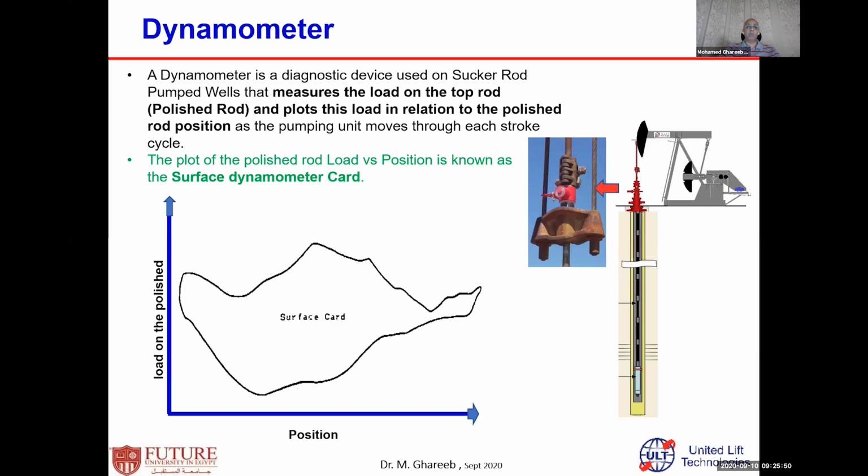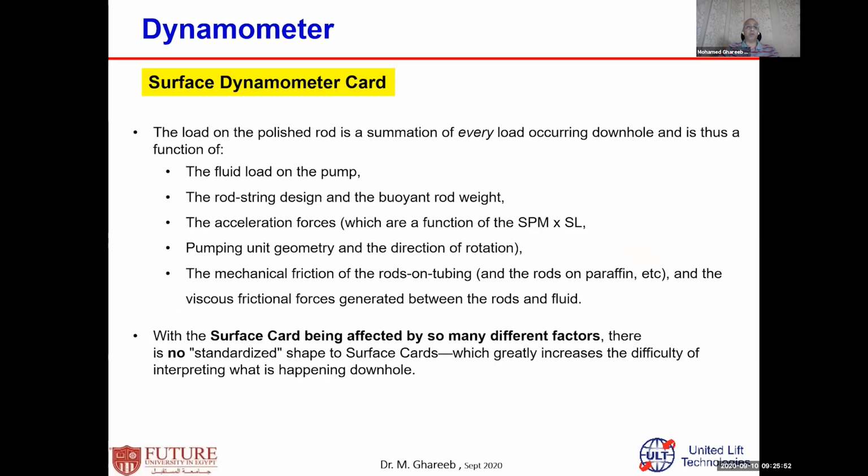However, the surface dynamometer card is the first point in dynamometers, and it is also affected by the pumping unit geometry. Remember, I informed you that for the pumping unit, there is different geometry. There is class 1, class 2, class 3, like conventional pumping units, enhanced geometry.